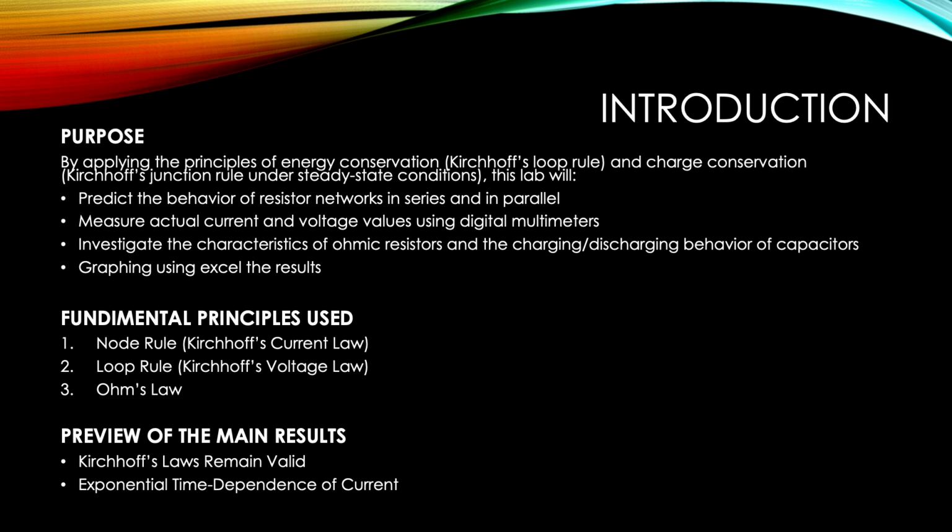The fundamental principles used are the node rule, which basically says at any circuit junction, the sum of currents entering equals the sum of currents leaving. The loop rule, which says in any closed circuit loop, the algebraic sum of the voltage drops and rises is zero. And Ohm's law, where the voltage across a resistor equals the current in it times the resistance. The preview of the main results is that Kirchhoff's laws remain valid, along with the exponential time dependence of current.